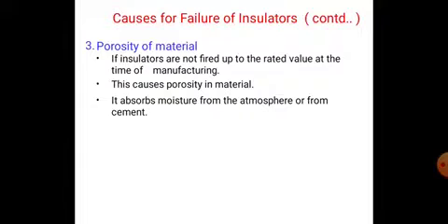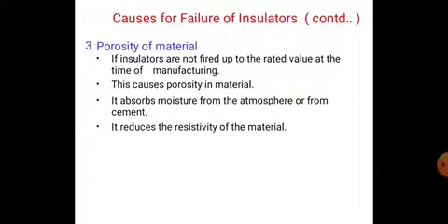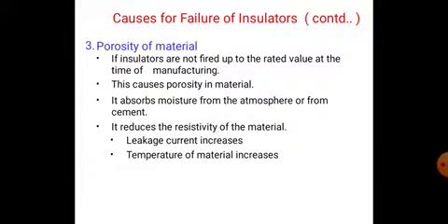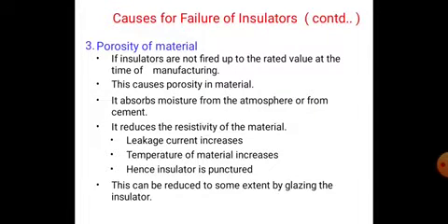It absorbs moisture from the atmosphere or from the cement. It reduces the resistivity of the material. Leakage current increases, and the temperature of the material increases. Hence the insulator is punctured. This can be reduced to some extent by glazing the insulator.